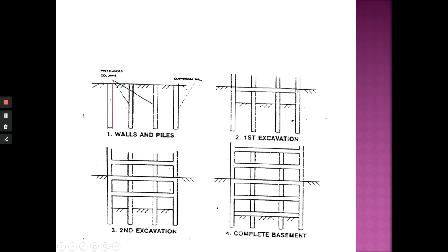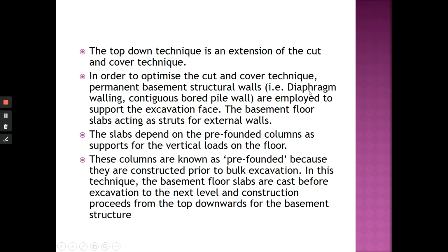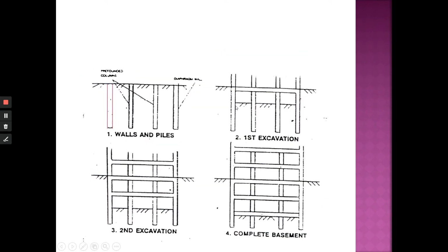And this slab actually serves as the strut. They don't really need strut or rod or braces, but when they construct this slab, it serves as the strut. It will hold the retaining wall at the sides. And once this is completed, they will then excavate the bottom part. And when they are excavating here, they can actually also start constructing the superstructure,